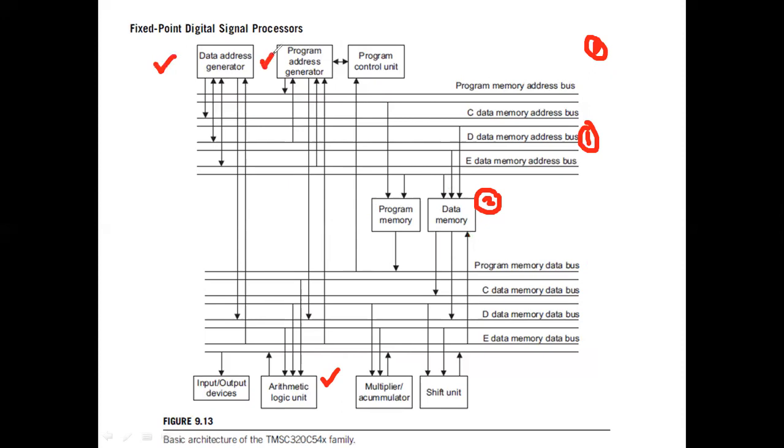What is this address generator? You might have seen this particular thing, right? Say you wanted to loop through some set of instructions 20 times. Then what do you do? You will initialize some pointers, increment the source pointer by 1, increment the destination pointer by 1, decrement the counter by 1. That's what you would do, right? Who would do this particular incrementing? Usually the load would have been on the normal ALU. So while you do this petty incrementing, all the other processes have to wait.